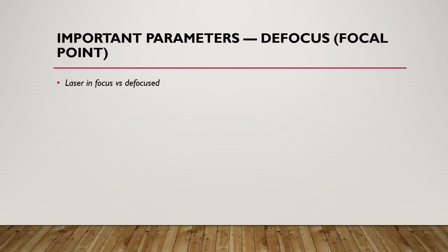But if you defocus too much, the energy drops significantly, so there is not enough heat to turn the substrate into graphene. So you have to tune that too. Every laser is different. A carbon dioxide laser has a different defocus point, which gives the optimal quality of graphene.